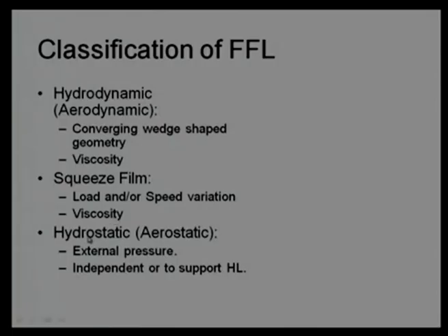Last one in this category is a hydrostatic. Again in bracket is written aerostatic. Hydrostatic for the liquid, aerostatic for gases. Here the pressure is supplied, we need to provide external pressure to levitate one surface relative to other surface.